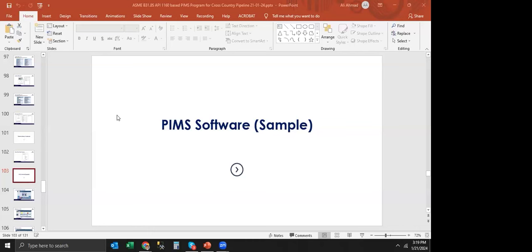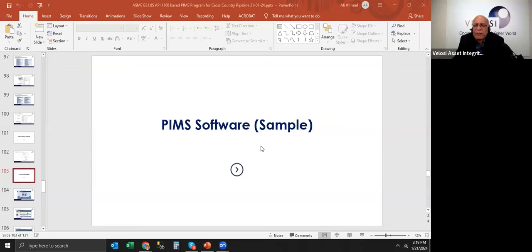I'm just asking whether this ASME B31.8S is used for the normal gas pipelines connected inside the countries, like from SSGC to our home, or is it mandatory for the connections between the countries. No, see, ASME B31.8S is integrity management for the gas pipelines and networks. So it covers both: the complete SSGC, SNGPL gas network pipeline and piping distribution network is covered under this standard.